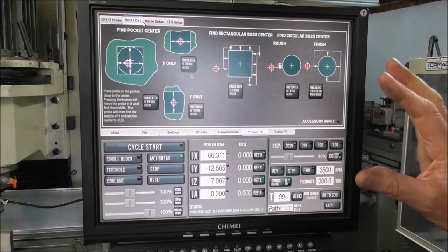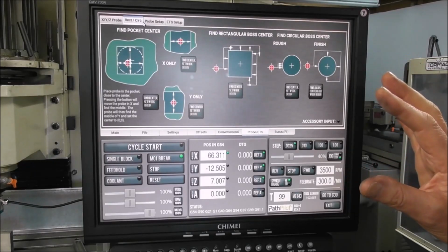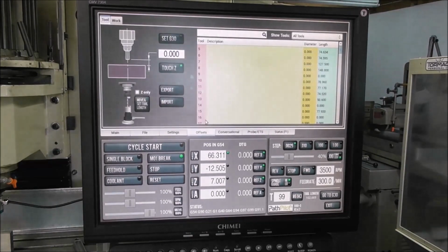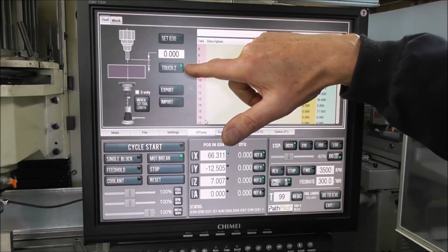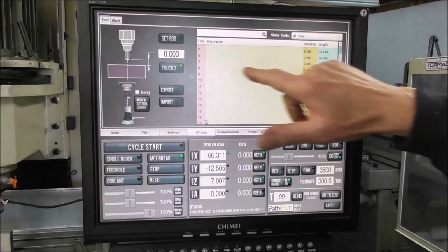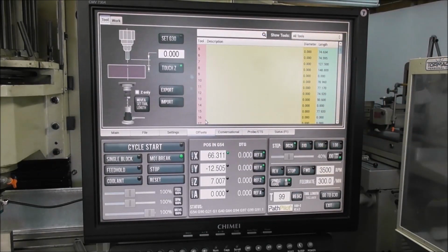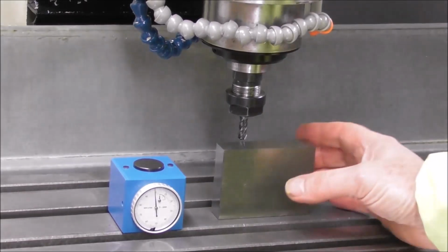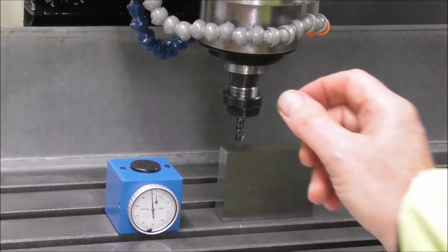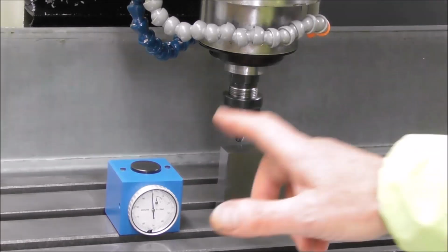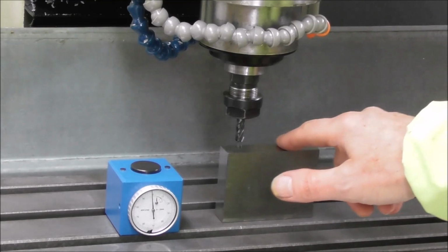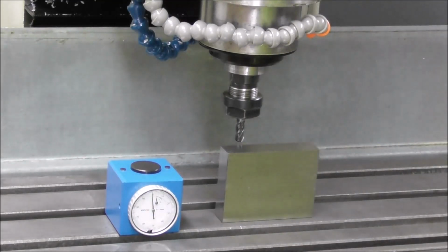Less critical to have an electronic tool setter, because it's really only a one button push on the offsets page. On the tool offsets page, you're just pushing this touch Z button and it loads it automatically into your tool offsets table. Okay, so to complete the circle and do the final test, we've set tool number 6 to 74.59 with the dial indicator setter, and we've set the work offset with our probe. So let's just make sure it's correct.